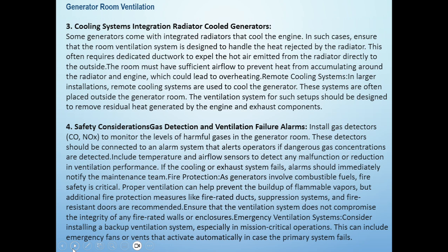The room must have sufficient airflow to prevent heat from accumulating around the radiator and engine, which could lead to overheating. Remote cooling system. In larger installations, remote cooling systems are used to cool the generator. The systems are often placed outside the generator room. The ventilation system for such setups should be designed to remove residual heat generated by the engine and exhaust components.